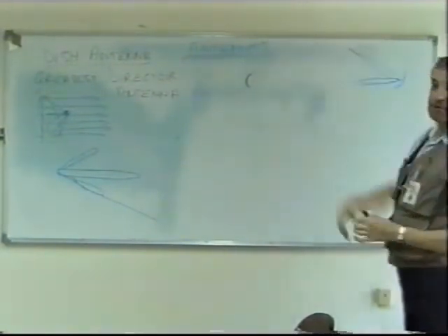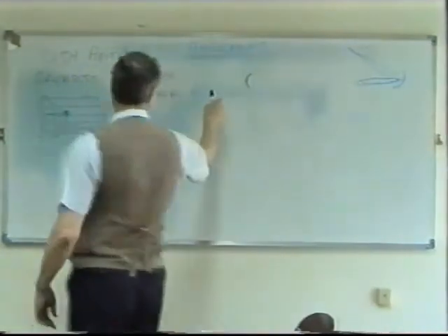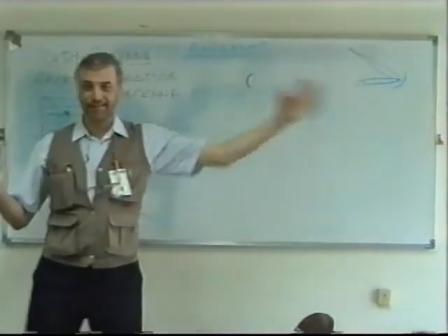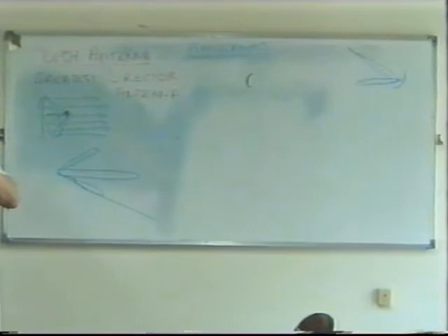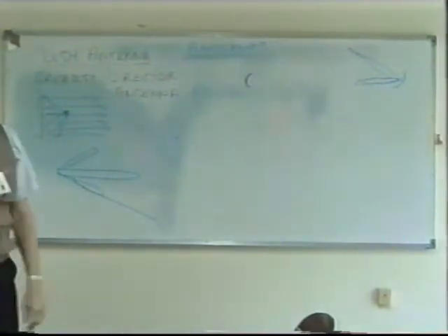And that's your alignment. Of course, what makes it more difficult is this guy's got to do the same. Over these distances we're talking about, first of all, one guy will have to do it, and then the other guy has to do it, to get his signal, and then this guy has to do it, and they have to keep repeating. And of course, the other thing is, it's not just up and down, it's also left and right. So it becomes quite a bit of a problem getting these dishes initially aligned.